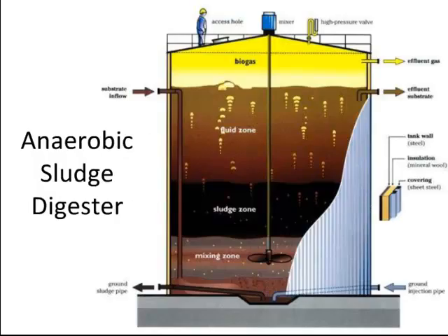So the effluent portion of the waste was the liquid portion. That liquid portion was separated from the solids by primary treatment. It then went through secondary treatment, where microbes digested it and used all of the waste in there as food to generate more microbes. Those microbes were then settled out, collected from the liquid, leaving just the water.